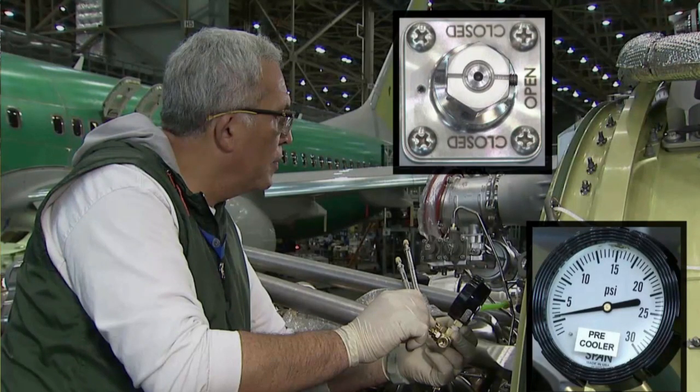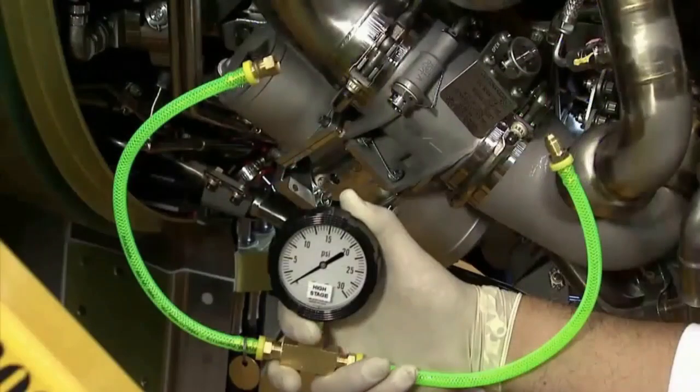If the PCCB does not open to the AMM requirement, you must replace the PCCB. Note that for the sake of this test, if the PCCB opens to within 30 degrees to fully open, it is considered open. A good reference to use is the inside of the screw head on the valve housing.